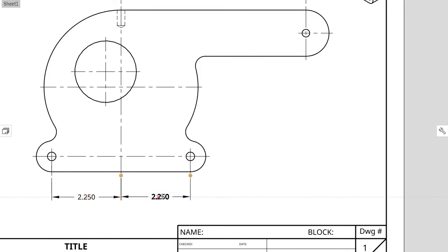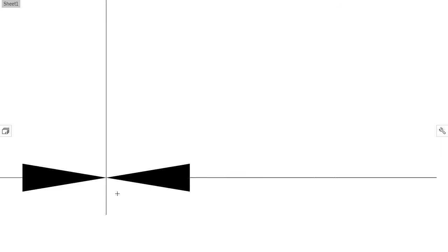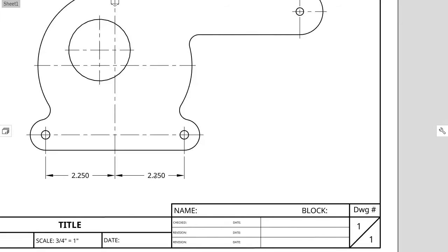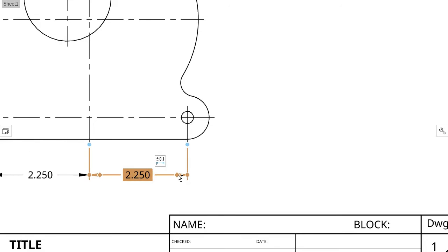And you'll notice that as I place dimensions, they can snap to other dimensions. So I want to make sure that those dimension lines really line up nice and neatly. And I can always hit escape and get back to my cursor. I can select a dimension and I can move that dimension around. Obviously, I can move it further away, or I can make sure that they are snapped. There's the handles to the actual arrows. So I can click these handles and push the arrows to the outside or push them to the inside.